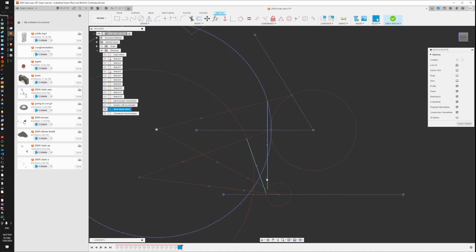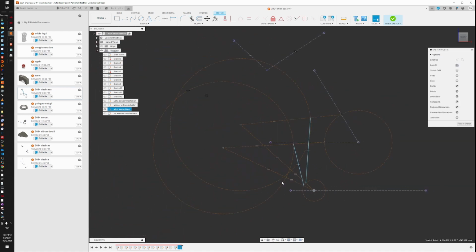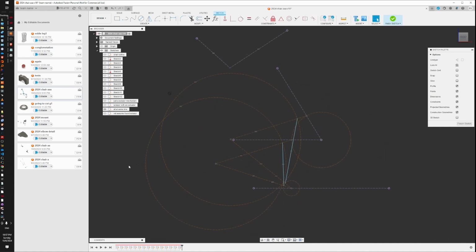Okay, so now I should have, what's the word? Abstract kinematic design. So I can choose any of these locations and it will solve itself, or it'll break itself because there's technically a toggle point here. So there's this entire continuum of possibilities. I think there's two or three degrees of freedom. But let's say that for aesthetic purposes, I want this to be about halfway between these two lines. So I can manually put that here.